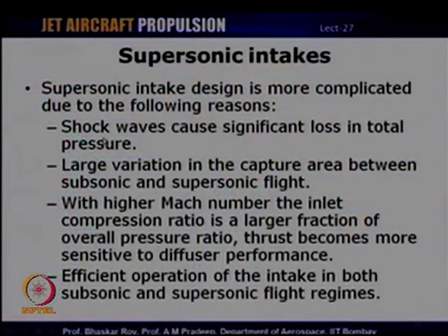So, let us take a look at what are the different reasons which make the operation of supersonic intakes much more complicated than subsonic intakes. Now, one of the major concerns or issues that affect the performance of supersonic intakes is the presence of shock waves, which is obviously something that is required, because deceleration from supersonic to subsonic is possible through shock waves only. So, you definitely need shock waves for deceleration, but these shock waves also cause significant loss in total pressure, and it is one of the challenges to try to minimize this total pressure loss.